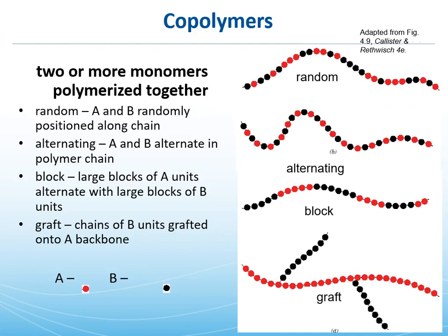And it's a combination of block and graft, and the polarity difference is so much that the one type of very polar polymer, it's so polar it's actually a superacid, ends up forming its own phase. The entire molecule kinks around such that that very, very polar group literally forms its own phase and becomes continuous when it's soaked in water. And the remaining groups are Teflon, one of the most non-polar materials that we can get in the polymer world. And it's that combination of polarity and non-polarity and the continuous phase of the polar phase, which can attract quite a bit of water, that gives it its unique properties.